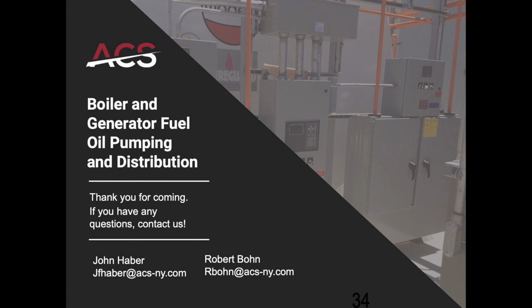If the tank is vented into the atmosphere, what's the reason for the tank to be rated at 5 psi or New York City 25 psi? So the reason, UL 142 rated for 5 psi, New York City approved is 25 psi. Let's say you have a UL 142 tank in the basement of the building, and something goes wrong in the fuel oil system, and that day tank begins filling up with fuel. It starts going up the vent. You're creating a back pressure on the day tank. And when it gets over 5 psi, obviously things are going to break.